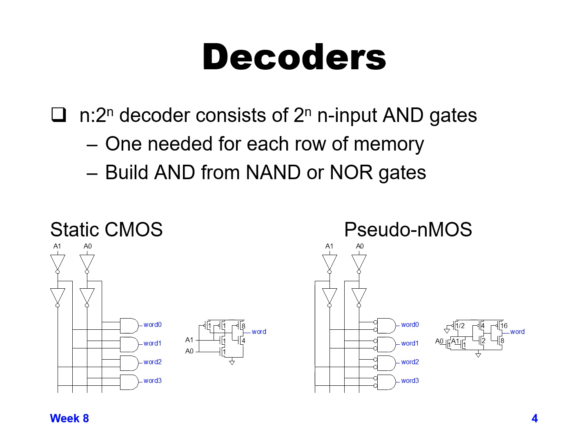We use that because the word line is generally driving multiple bits, if we have like an 8-bit word or maybe a 16, 32-bit word, we're driving a fair amount of capacitance. It's done most efficiently with an inverter rather than a NAND gate or a NOR gate.